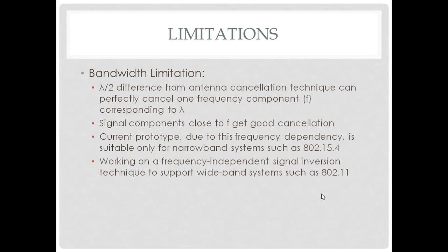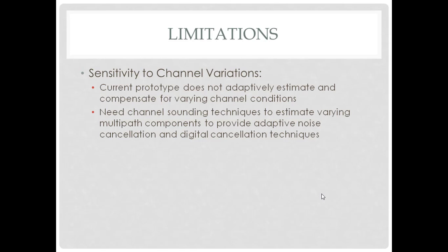And we should work on a frequency independent signal inversion technique to support wideband systems such as 802.11. Also, this prototype does not adaptively estimate and compensate for varying channel conditions, and we need channel sounding techniques to estimate varying multipath components to provide adaptive noise cancellation and digital cancellation techniques.